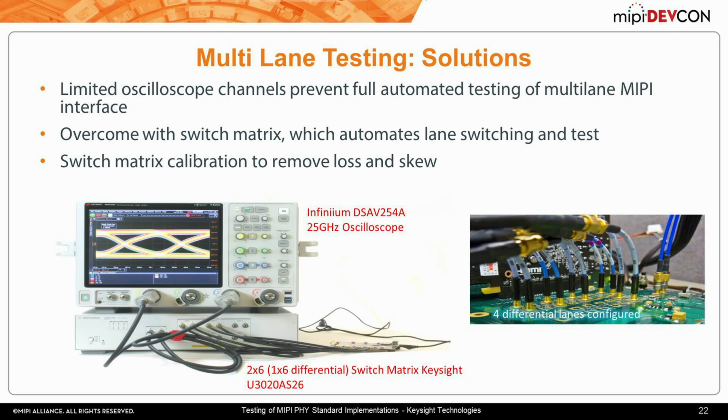So what you really want to try to do is still to use good cables, low-loss cables, have a low-loss switch. You want to try to keep these cables as short as possible, and that's going to be beneficial to you in your test environment.